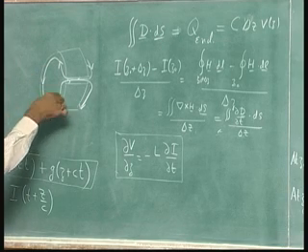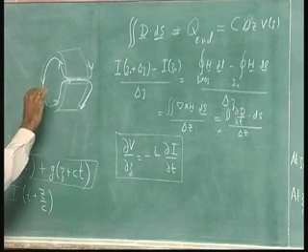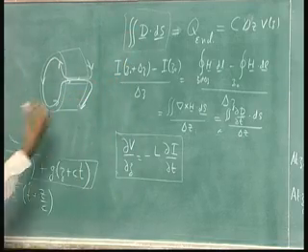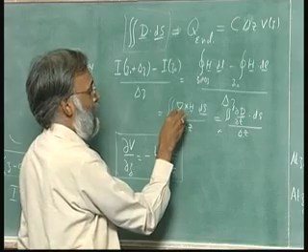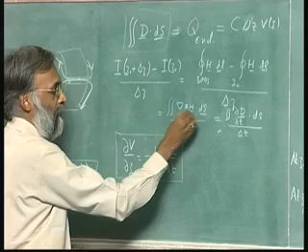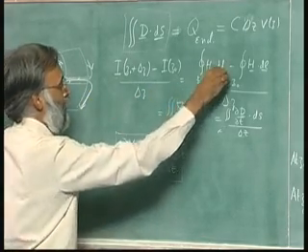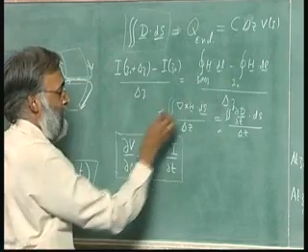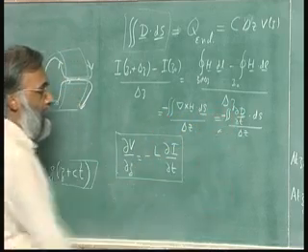when I do the right hand rule, I am talking about flux entering this surface, whereas what I count by d dot ds is the flux leaving the surface. Therefore, there is a minus sign when I connect up the loop integral h dot dl and curl of h dot ds. So what I have here, h dot dl at z plus delta z minus h dot dl at z is actually minus of curl of h, which is minus of del d del t dot ds.